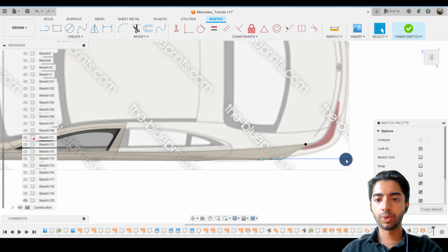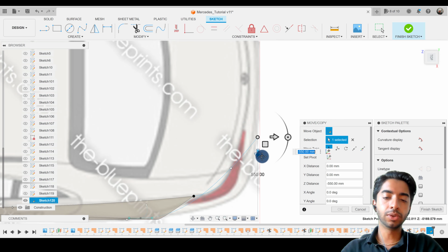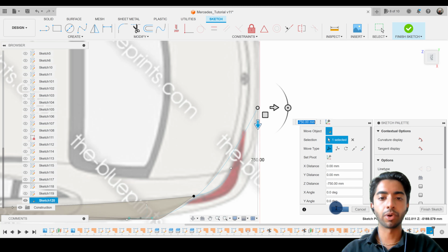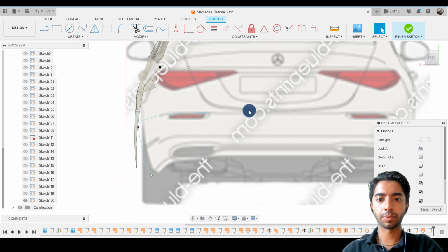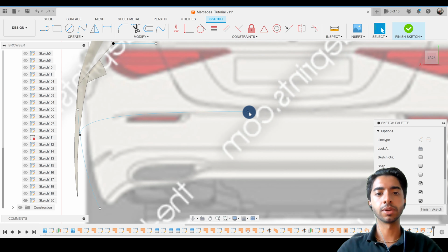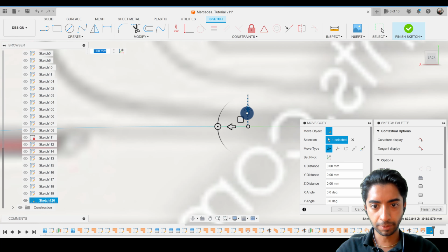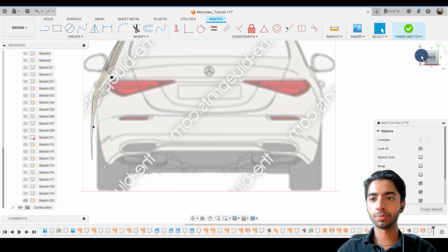Go to the top view, and we can align this now into its place. So I gotta admit, it's usually easier to maneuver the 2 individual points before you start dealing with the tangents. And this sort of helps with a little bit of clarity as to how the end product might look. So let's go ahead and press OK for now. And let's see if this looks correct from the side. It does, and look at that, it's actually landed in a pretty good position. So maybe all I have to do is just pull this down very little, maybe like that, and press OK. So it's created that geometry there.